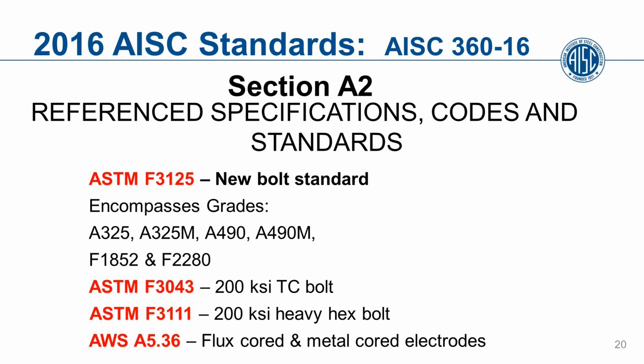AWS A5.36 has also been added. This is a new standard that will be replacing AWS A5.20 and A5.29. As these get replaced, A5.36 will be used.